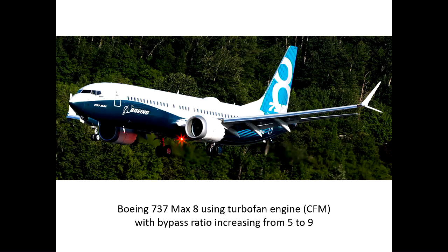The 737 started, I do not remember exactly, somewhere around the 1990s. So it started earlier, but over the years it has been improved gradually. This new model, in terms of performance, is actually pretty good. Compared to the previous model, it increased the bypass ratio from 5 to 9, and that gives a fuel economy improvement of about 10 to 12%. That's a pretty large saving.